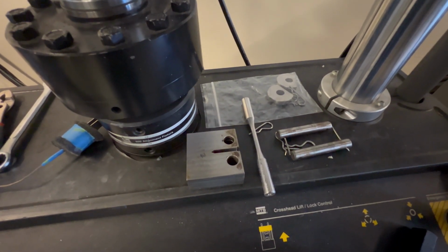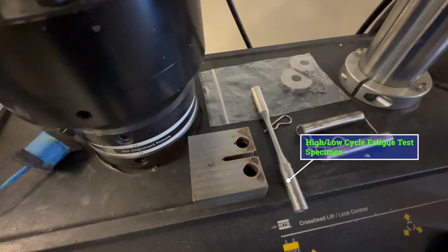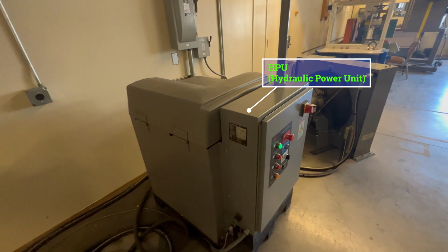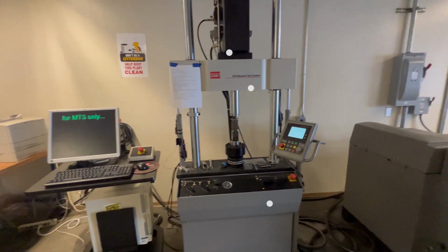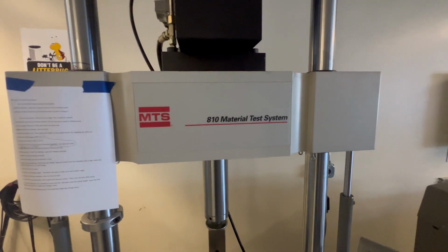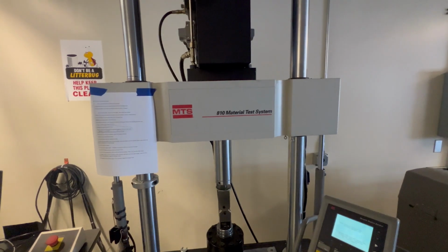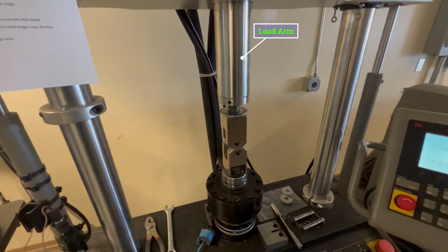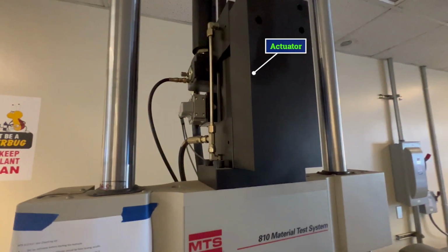Here, you can see we have the K1C specimen on the left and the fatigue sample, the cylindrical dog bone, on the right. The testing system has several main components, like the hydraulic power unit here, providing the load source. In the middle, it has this wide crosshead holding the actuator driven by the hydraulic power unit to apply the load to the samples. The load arm of the actuator can be programmed to move in a single direction or in a reciprocating motion under desired frequency and load.